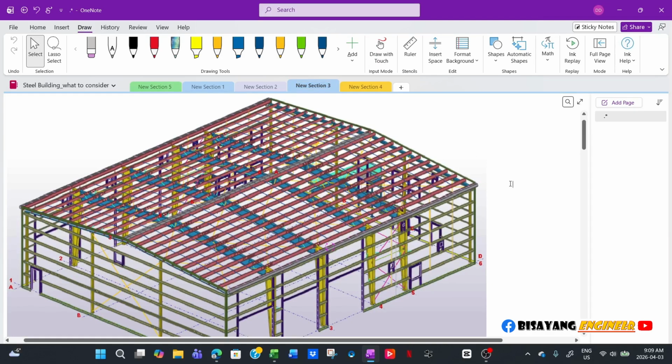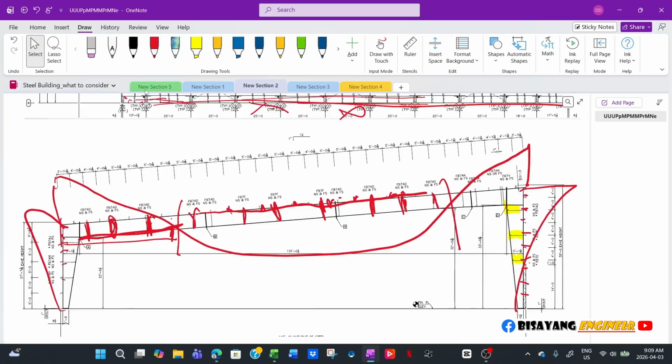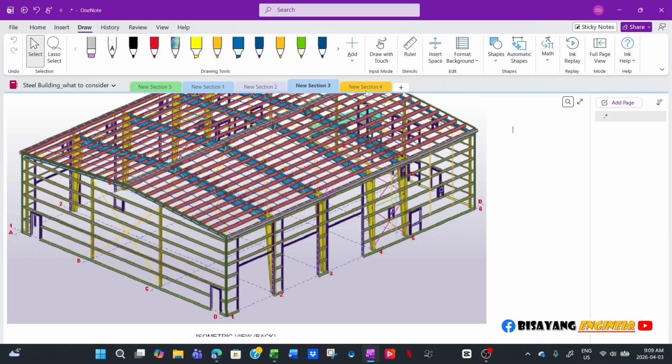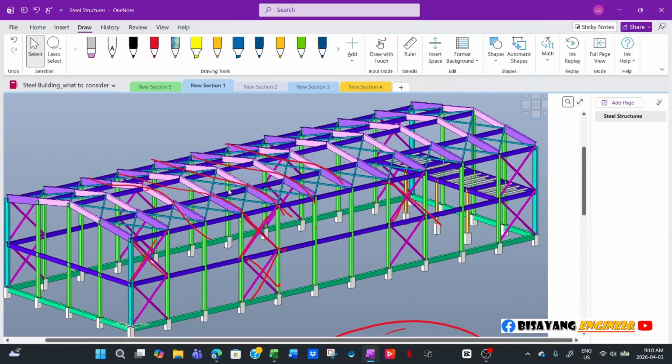Now, we already discussed the stress and the bracing, and then we will discuss the foundation for equipment, because he was also asking about that. I asked him whether those equipments are static, or whether they will vibrate, you know, dynamic loading.